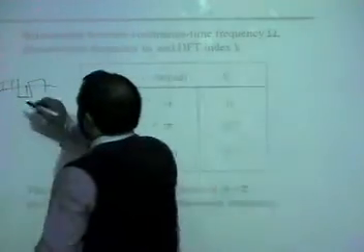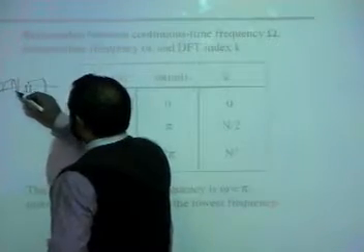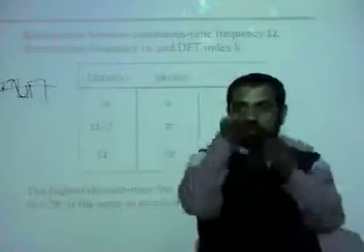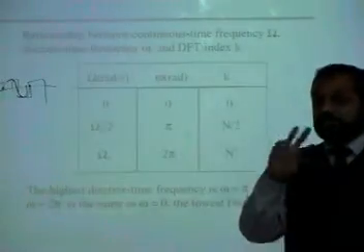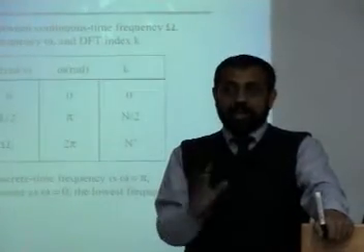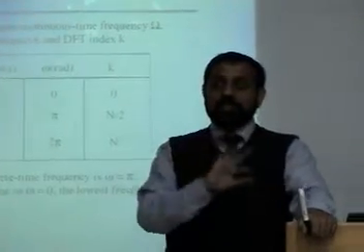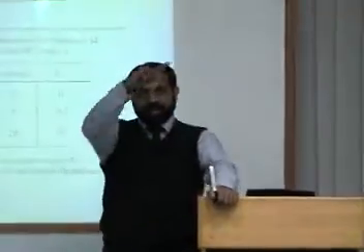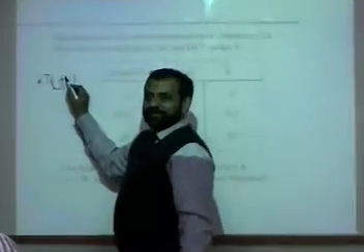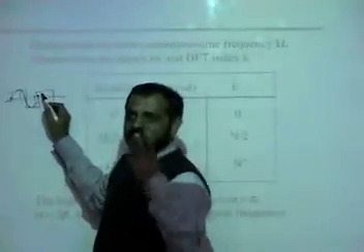Because no, it will be 1 over 2 kilohertz. Why? Because look, this is 1 cycle. Okay, 2 bits is 1 cycle. So this is how it is related. You say 1 megahertz, 1 megabit per second. What is 1 megabit per second? A signal is changing how many times? 10 raised to the power 6, worst case scenario, 10 raised to the power 6 times in a second. So there are how many cycles? If a change is a cycle, so there will be half the number of cycles.